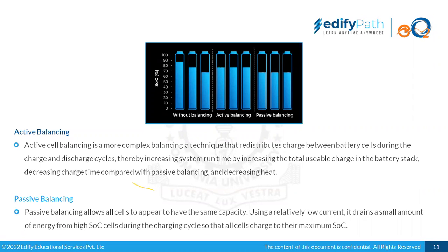Okay, so during charging and discharging, the same amount of charge can be utilized to be distributed among other cells which are at, say, a lower charge or lower voltage level. It would be given to them, and uniformity would be achieved when all the cells have reached a particular voltage. So this happens. Active cell balancing is a bit complex, because you can imagine that distribution would again need a lot of iteration, a lot of programming.